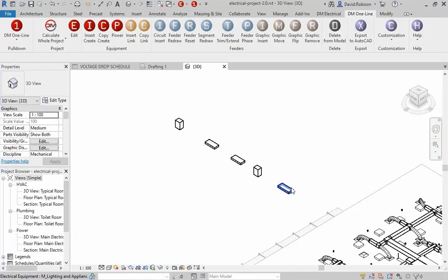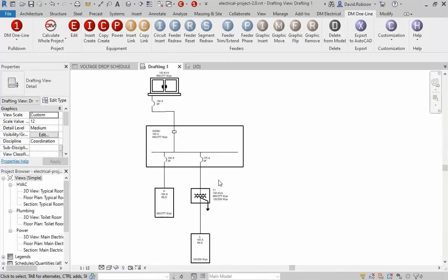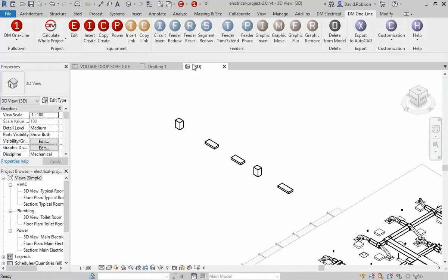The assumption is at this point, you might not even have a model from the architect. So you don't have anywhere to place these, but the way Revit works, it really wants to know what size that transformer is and where it is living in space, and the sheen, and whether it's a matte or glossy transformer. So, okay, fine, Revit, we'll put that in there, but we don't know where it is yet, because that's just not where we are with the design. So in terms of the electrical design, you're building out your one line, and then where stuff goes in 3D, you'll handle later.